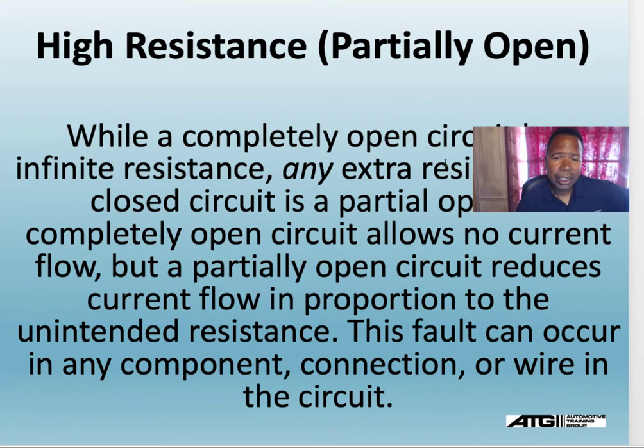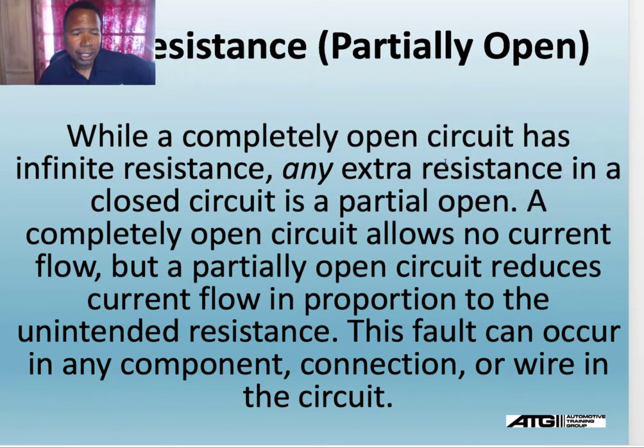A completely open circuit has infinite resistance. Any extra resistance in a closed circuit is a partial open. A complete open circuit allows no current to flow. That means there's no connection at all. I can have a lot of corrosion between two points, the center cable, center post, and a battery cable, but they're not touching. That's an open. But a partially open circuit reduces current flow in proportion to the unintended resistance.